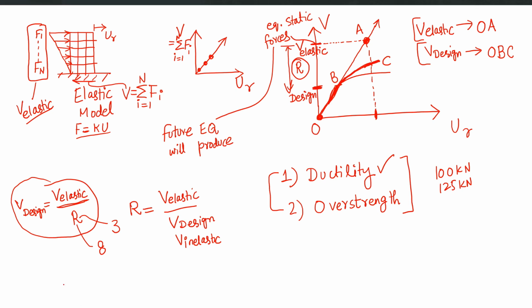So from the same table 12.2-1, you will pick not only your structural system which is permitted, you will also pick this R factor associated with that, and that will be playing its role in all three elastic model based seismic analysis procedures.